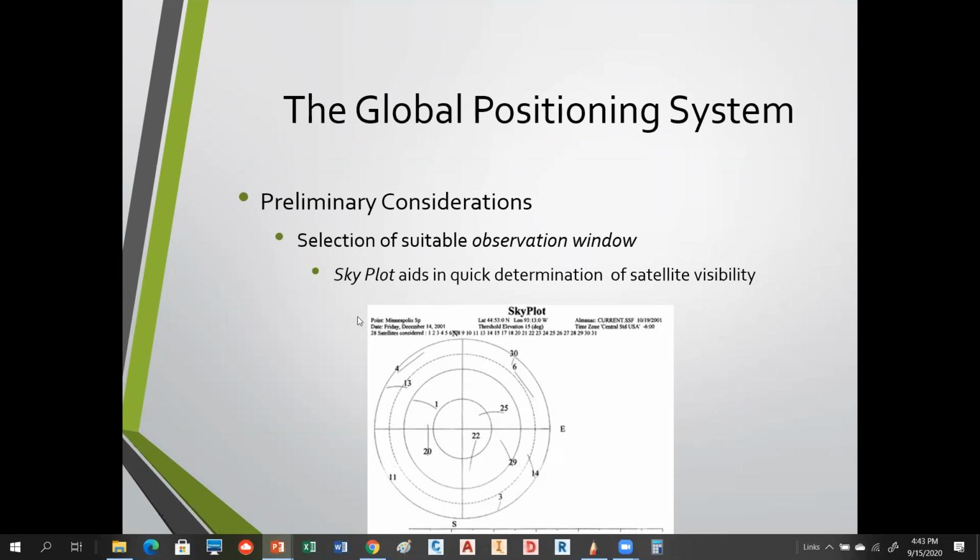So yeah, this is a cool little thing though. This sky plot. In my experience, I've done a lot of little stuff where I'm using a handheld one, but on the sky plot, routinely you're probably getting 12 satellites or more, where we're working a lot of times. And you can see you're getting quite a few, but that mask is kicking a lot of them out.